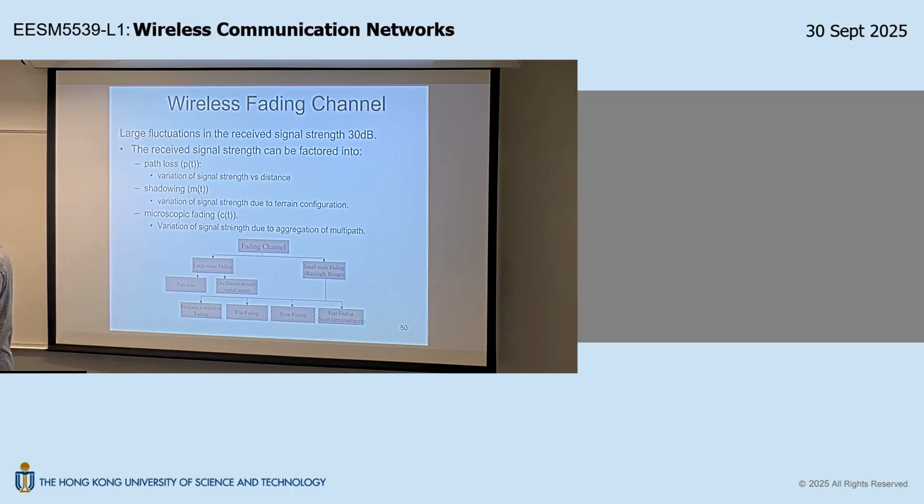Is that okay? The other way is to look at the transmission line equations. Again, the PDE is time invariant. The coefficients of the PDE are constants, independent of time, okay? So this gives you the confidence that this is also time invariant. So you need to check this before you can safely use this LTI model to do a black box modeling of your coaxial cable. Is that okay?